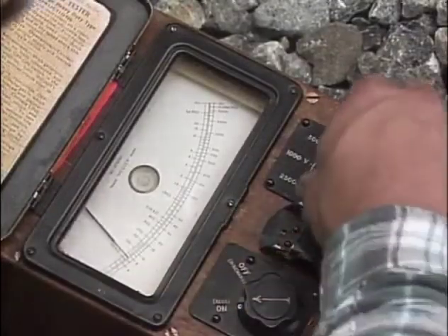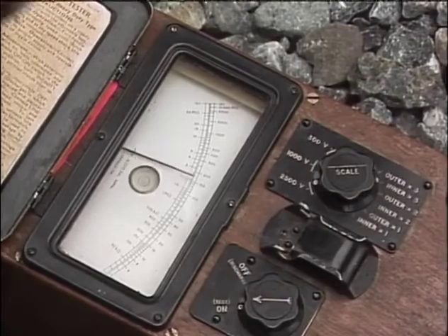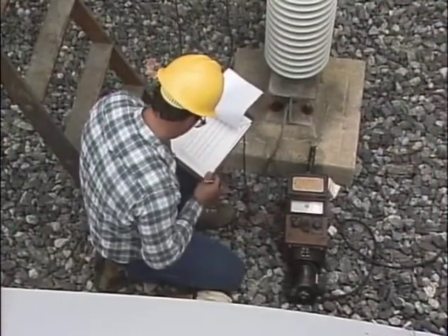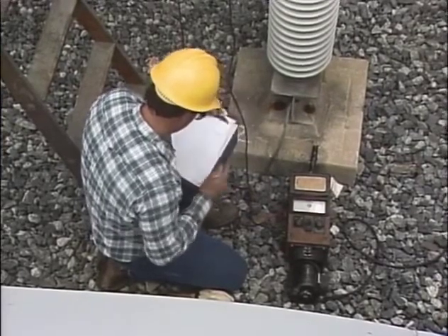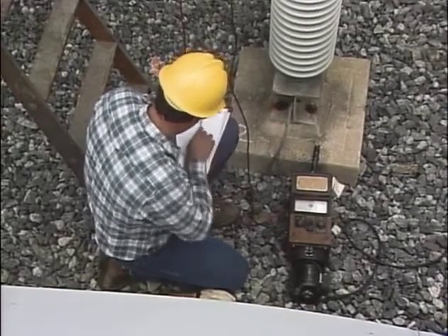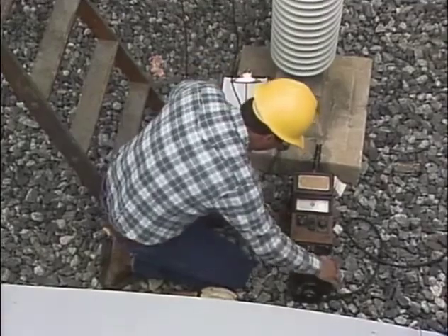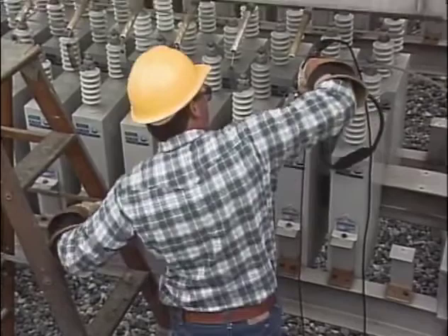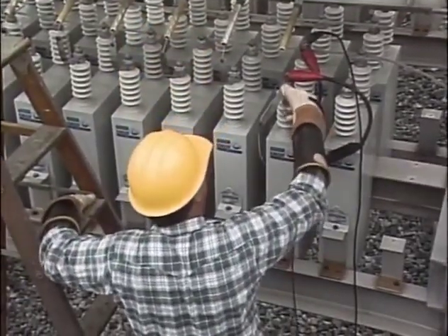With each voltage adjustment, the resistance indication is allowed to stabilize. After the last voltage adjustment, the indicated resistance can be compared to the rated resistance for the capacitor. The indicated resistance is documented. When the test is completed, the megohm meter is turned off. The capacitor is allowed to discharge for several minutes before the short is reconnected to the capacitor and the megohmmeter leads are disconnected.